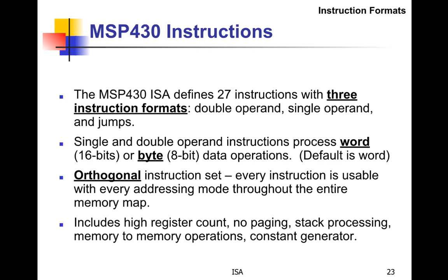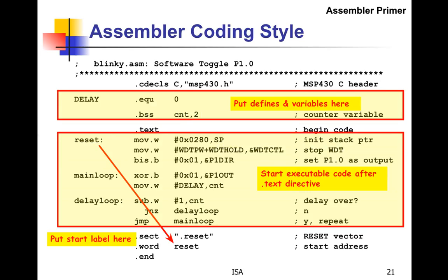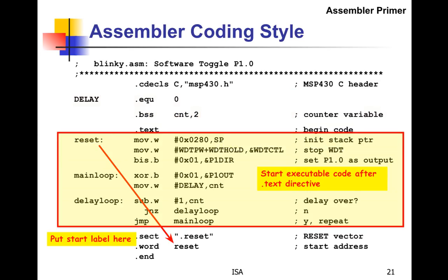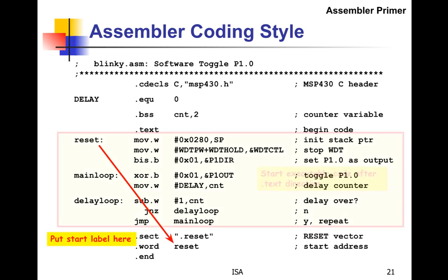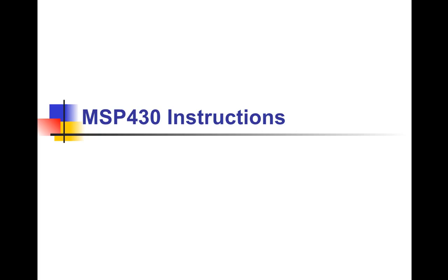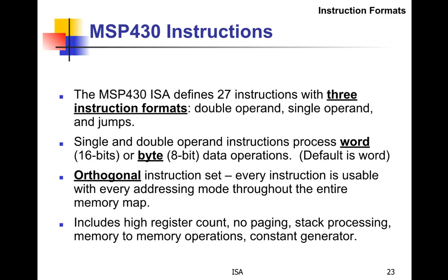You notice the last thing there was a .W. Where are we seeing that? Right, maybe up, yeah, right here, move.w, that means it's going to a word. So let's go back here. And if it said .b, then it's operating on a byte. The default is word, so if you don't put .w, it just assumes a word.